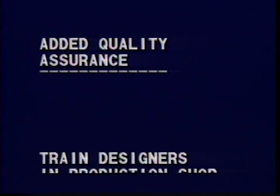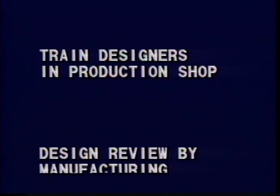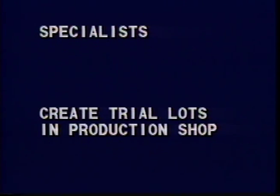We can provide added quality assurance by changes in the systematic approach. Send designers to spend time in the production shop to learn the realities. Establish design review by persons with wide experience in manufacture, or create separate trial lots under production shop conditions.